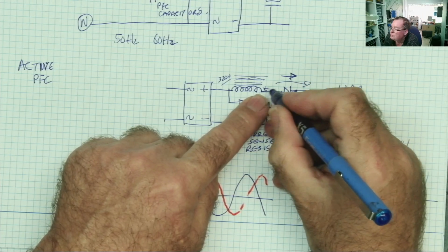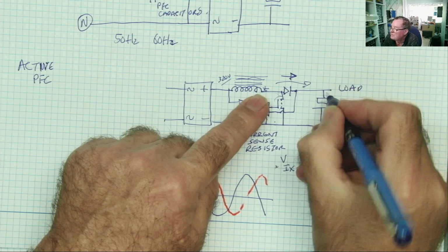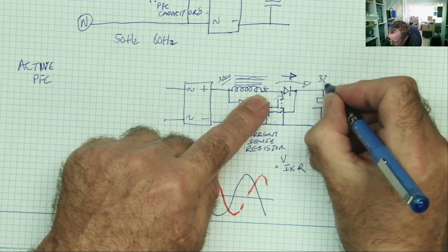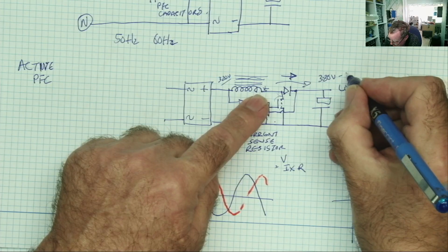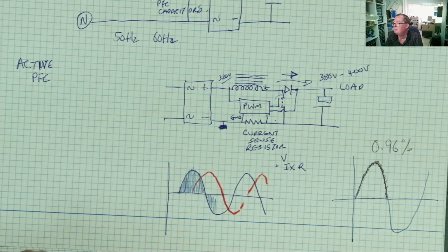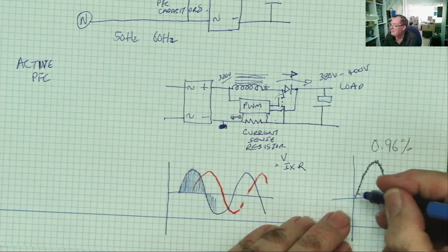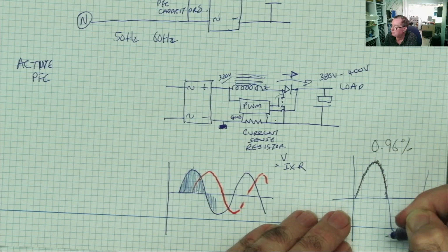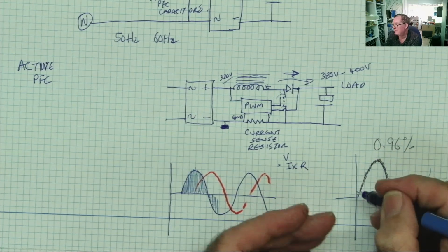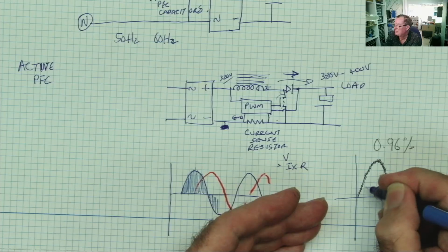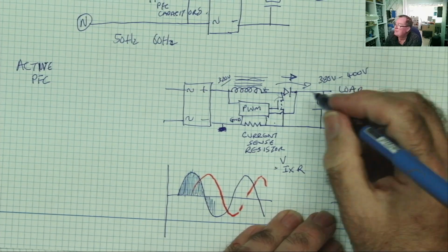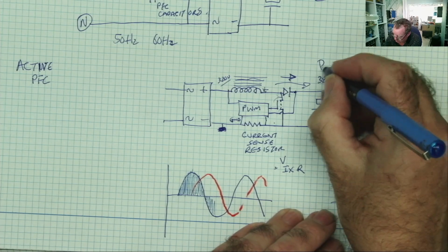So this boosted voltage goes through to the capacitor, but it can't come back. So the voltage on this capacitor will go to around 380 volts, up to about 400 volts, something like that. Okay, often 380. So as well as getting this current and voltage waveform almost in phase, even when it's not in phase, if you see what I mean, lots of little 90-degree shifts like that, yeah. As well as doing that, it also boosts the voltage, so it's a booster.